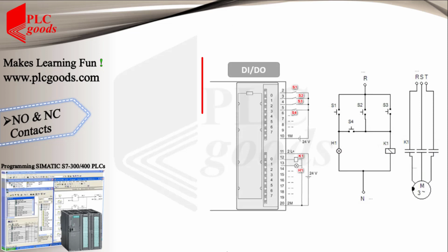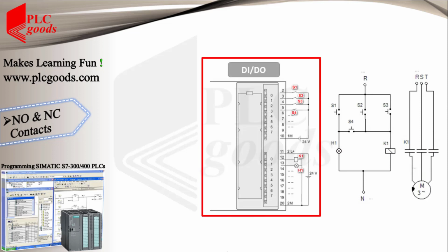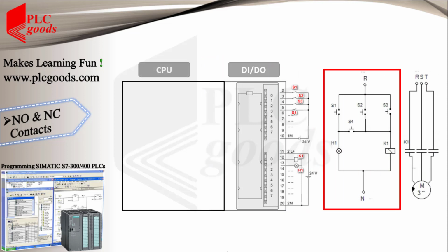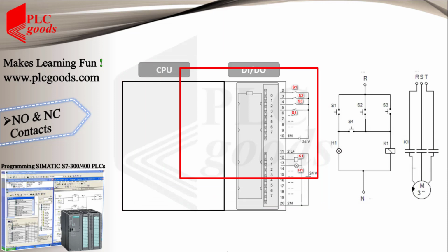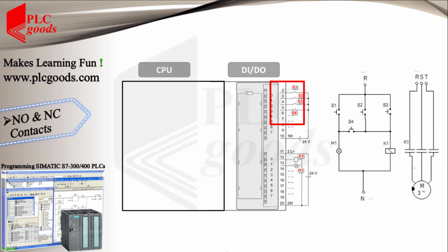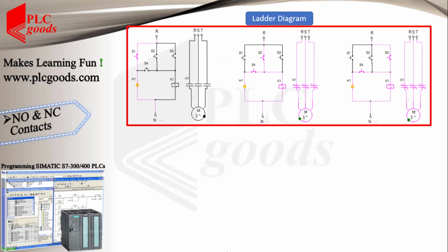Well, I can use an input-output module with this wiring diagram to implement the control circuit using a PLC station. Note that if normally open push buttons are used, the program inside the CPU will be similar to its equivalent electrical circuit. Also, two digital outputs are used respectively for the lamp and the K1 contactor that can turn on the three-phase motor. Well, these three states of the circuit illustrate all the conditions that the lamp can be on.